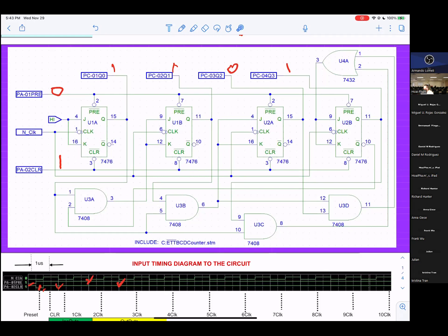And make sure pin 15 goes to here. That's okay. And make sure they go to L3 pin 13. And you can ring out anywhere the wiring is, to guarantee they're not connected to somewhere else. Also make sure you ring out pin 15 to the ground, to make sure they're not shorted to the ground. That is how you can fix the problem, guaranteed.